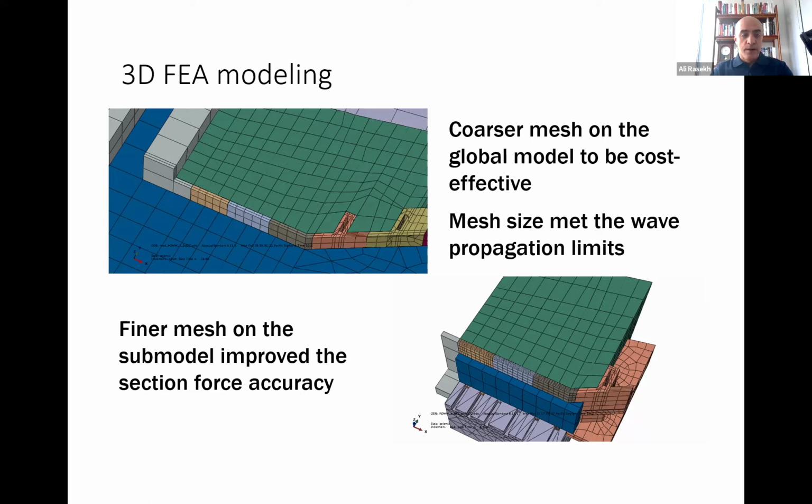So we were trying to save a number of nodes and elements. Based on today's standard, these are poor quality meshes. We could do a lot better, but we really studied whether 2 elements are good enough. If 2 elements can give you a good estimate of bending, then don't do more than 2 elements. A lot of energy was spent on putting in the minimum number of elements or nodes that can capture a good estimate of the response.